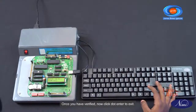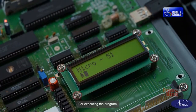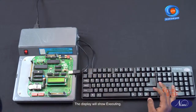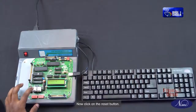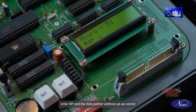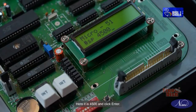Once you have verified, now click .enter to exit. For executing the program, enter Go, starting address, that is 4200, and click enter. The display will show executing. Now click on the reset button. For displaying the output, enter SP and the data pointer address as we stored the value in it. Here it is 4500 and click enter.